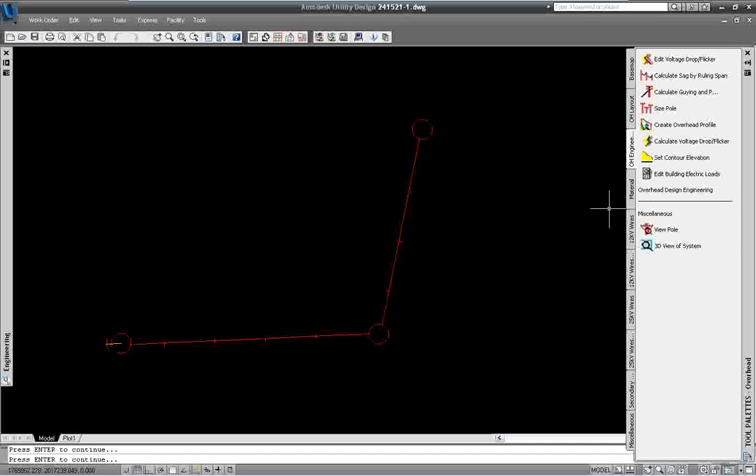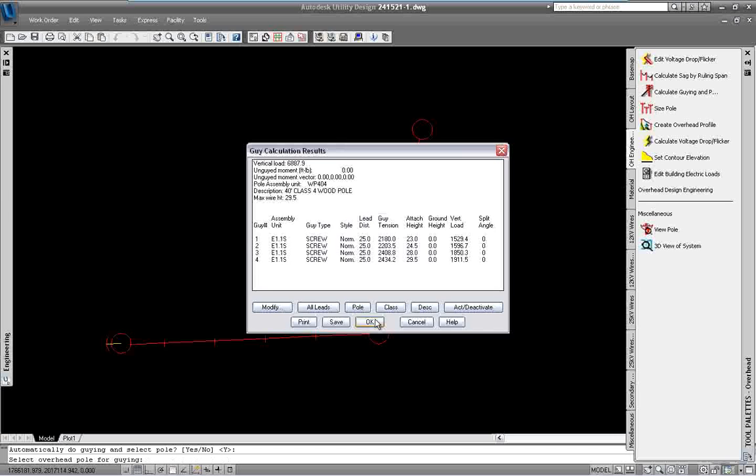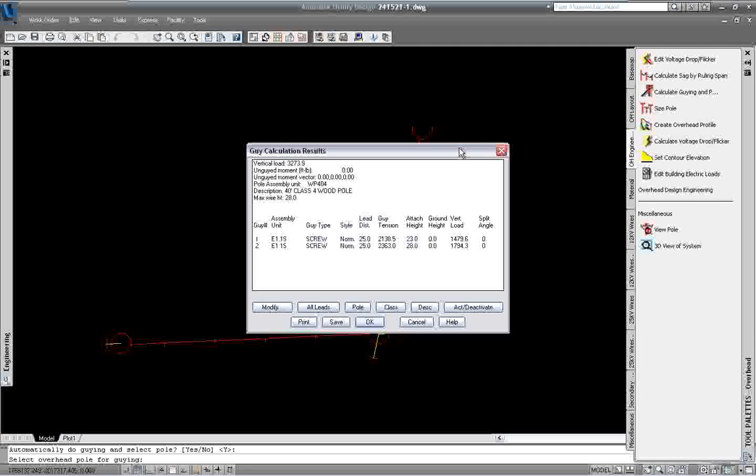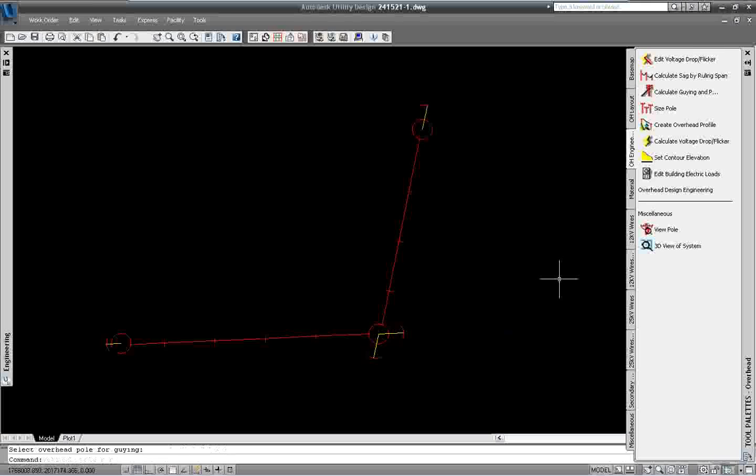Sure. That conductor data, where you're identifying the loading on the conductor, the pounds per feet, can those engineering calculations be configured for my utility? Because based upon my geography, I'm maybe not worried about ice loading on a conductor. Very definitely. The configuration for ice, for wind, will vary throughout the country, and it's all configured in tables so that the actual utility can make changes. You can even allow the individual staker to make changes. For instance, they're working in an area where there's only, for instance, a ½ inch of ice versus a ¼ inch of ice, and allow the user to make a quick change for an individual project.